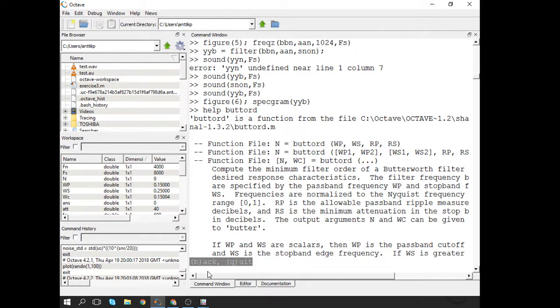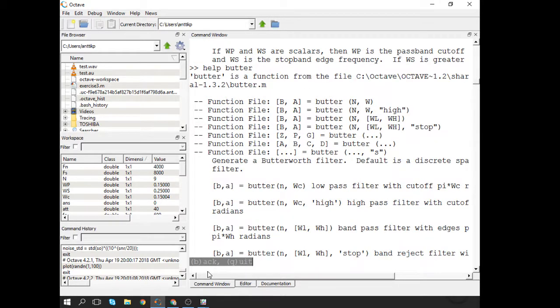Yeah, then you can do the estimate for high-pass or band-pass or low-pass design for the filter, and then you just need to make the corresponding design in here. Low pass is the default, but for high pass you can just plug it there, and then there's the band pass or stop band filter. But everything starts from the fact that you need to first do the estimate for the order number.